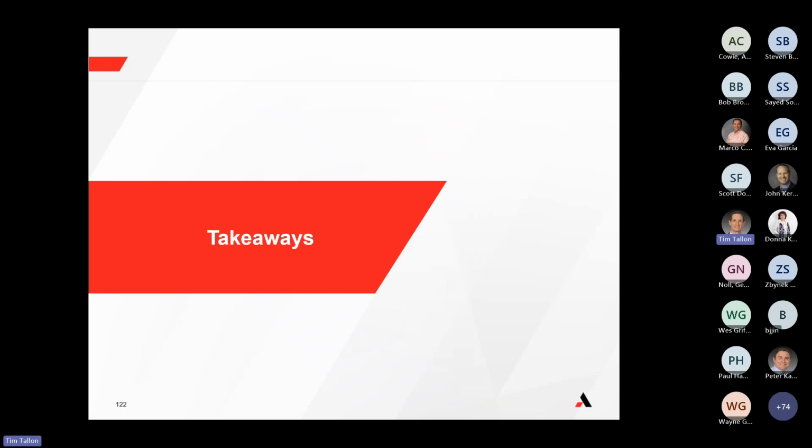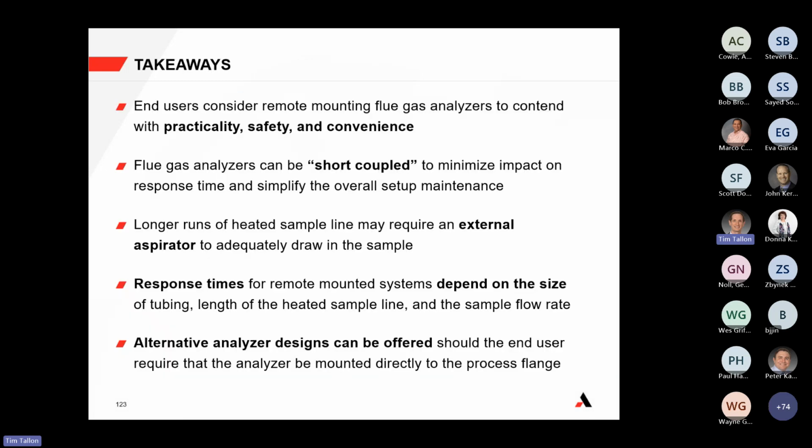So we talked about a lot today, and I really appreciate your time and your questions. Some takeaways, like I said, remote mounting really comes down to practicality, safety, and convenience. When it comes to short coupled installations, that's the least impact on response time. That's still a pretty simple, maintainable setup. For longer runs, we recommend an additional external aspirator to adequately draw the sample in, about 15 feet.